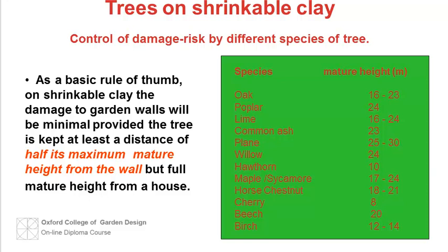A tree which is growing can remove water, causing subsidence as the clay dries out and shrinks. A tree which has been removed may have left a dry area which will swell or heave as it reabsorbs water over a period of years. This sometimes takes place over as long a period as 3 decades. Either way, the wall and its foundations can become distorted and cracked.